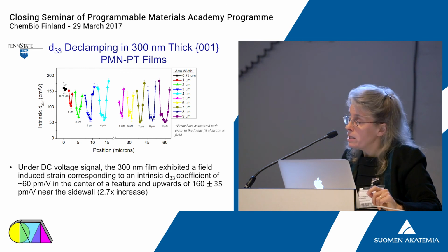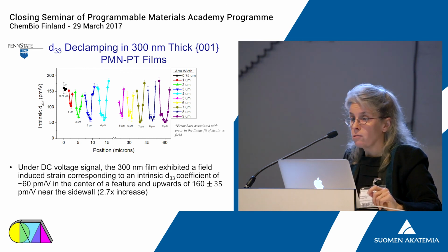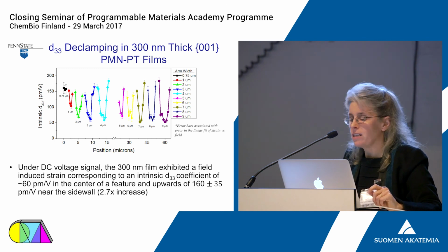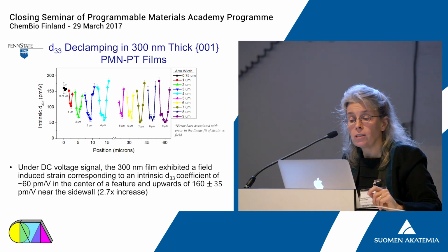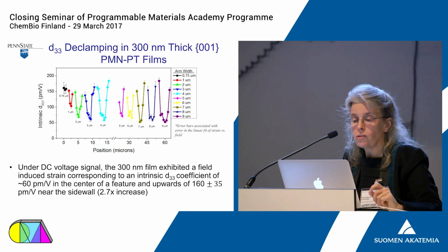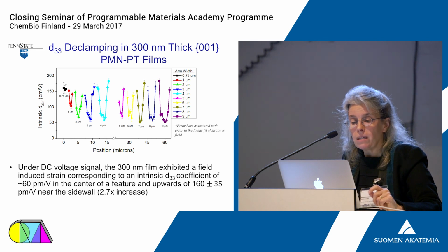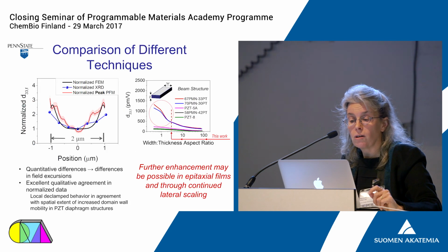We weren't able to measure our smallest devices because we literally didn't have a beam size that was small enough to do that. We were about 250 nanometers lateral resolution. But here are results on thicker, literally wider devices. And what you can see is that the values that we achieve on the edges of any of those feature sizes are declamped. And then the average piezoelectric response begins to climb once you get below feature sizes of about 2 microns.